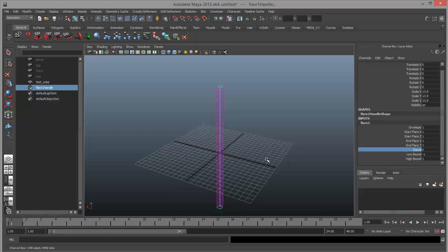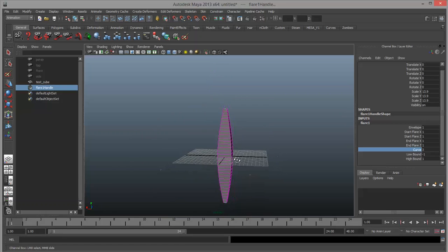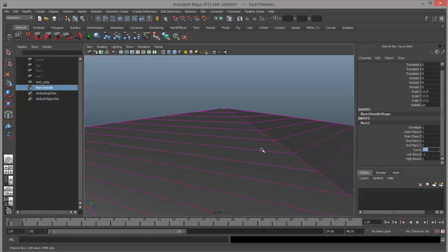So first I'm going to turn up curve, and you can see that it makes it fatter in the middle. So this is a better way to do that effect than the lattice because it is applied smoothly, in case you want to do that. By the way, I'm dragging this farther, but it stopped at 3 there, and I can go to -3. You can usually type in a larger number for these channels, even if it won't allow you to drag interactively to that number. So let me try 100, see if it goes there. Wow, it really did that.